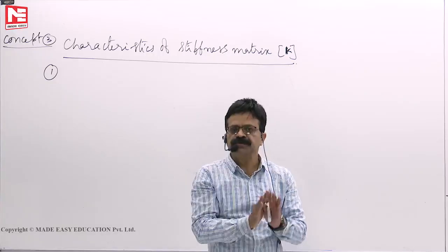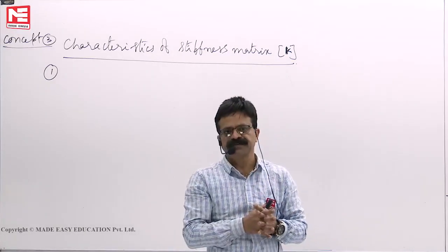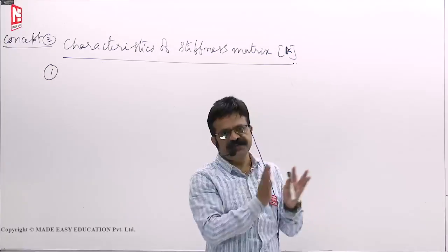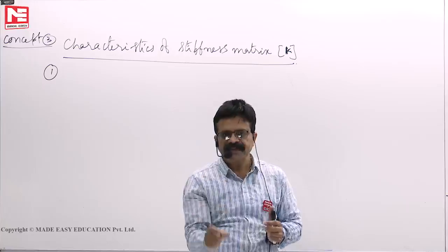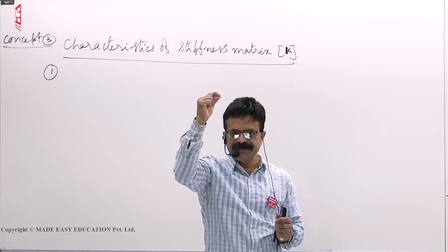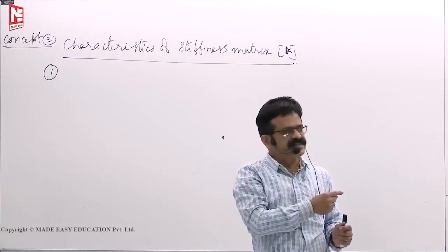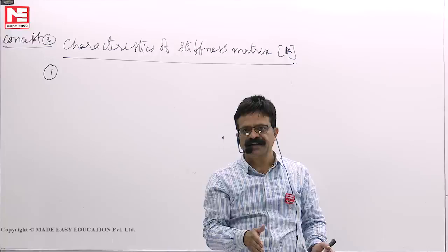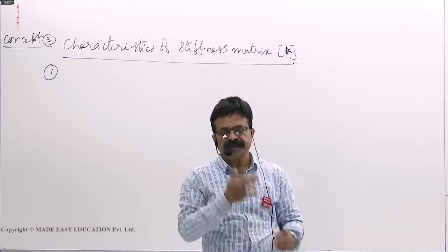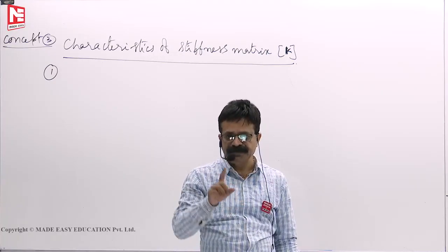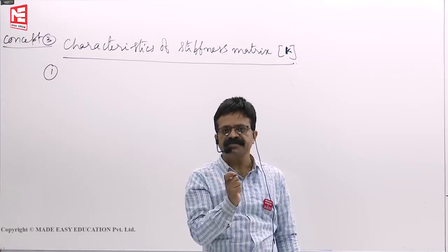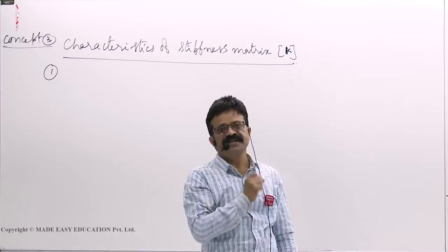To list them, you don't have to use Castigliano's theorem 1. Double time differentiation of strain energy not required. Strength of materials formulas are sufficient. Next, second column if you want, fix all the coordinates, only second coordinate give unit displacement. Because of that, what are all the forces developed, as I have explained, that will become second column. Like that, if you build, you will get a square stiffness matrix. To develop all the possible displacements, you have to restrain first, then give the displacements.